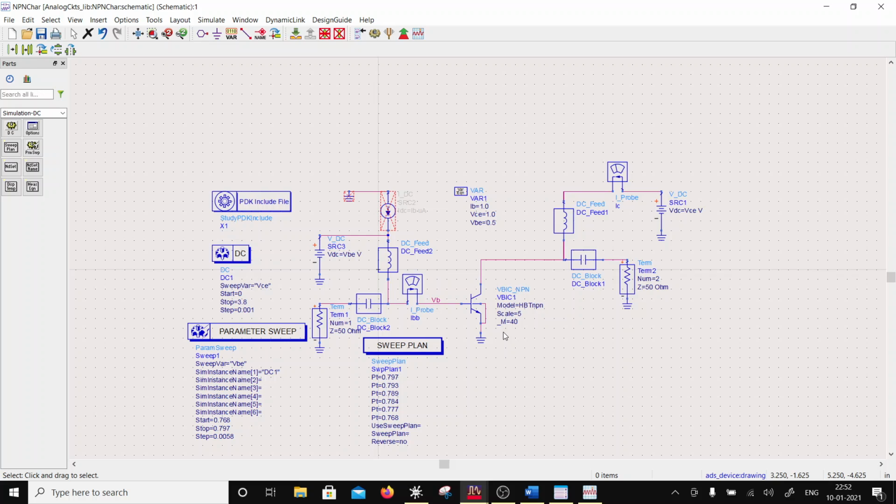Now that means that when you design an amplifier, biasing with the current source will give you a more linear transistor. And when you are talking about breakdowns, then biasing with the voltage will have an advantage because it will push out the thermal runaway. Okay, and then there is an intermediate way, which I will show you here.